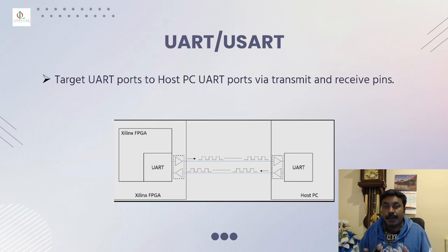This is a simple block diagram to illustrate how the actual communication happens. This example shows two UART communication ports in two different areas. Again, you have to first make sure your microcontroller and your PC are compatible to use UART or USART mode. Most PCs have serial communication, so you don't have to worry much, but it will still have that three-wire communication: the transmit, receive and ground.